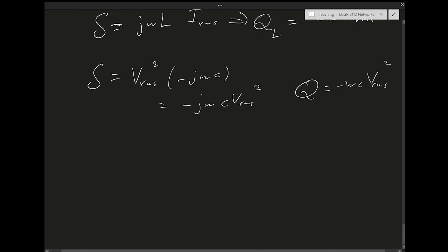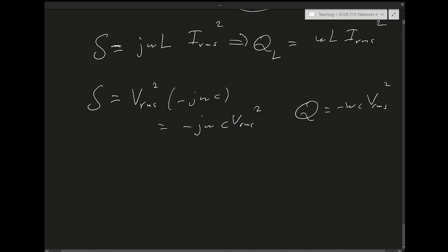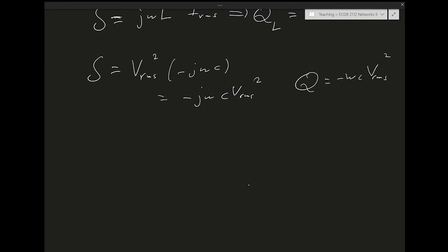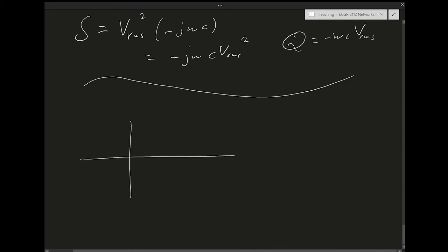Okay. So let me present this in another way. I want to give a graphical interpretation of complex power and power in general. We have V RMS, let's say. I'm representing the RMS value of the phasor. The current can be at any angle, so this is not purely inductive, capacitive or resistive. This is some random combination. The current is at an angle theta I, the voltage is at an angle theta V, and this angle here is theta V minus theta I.